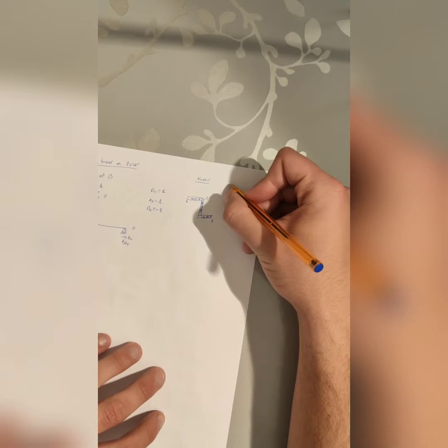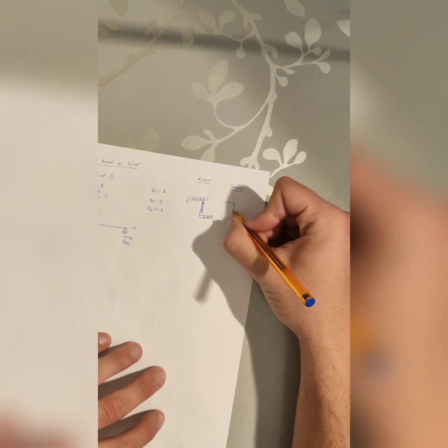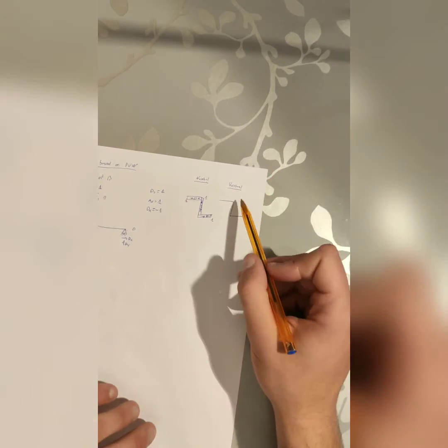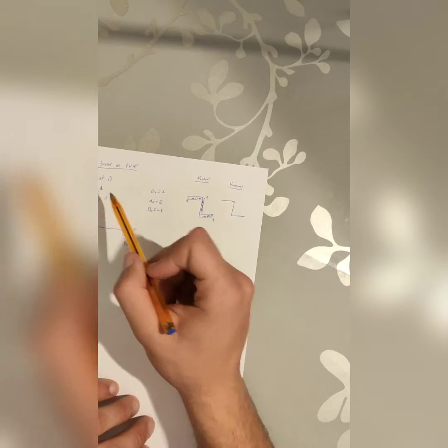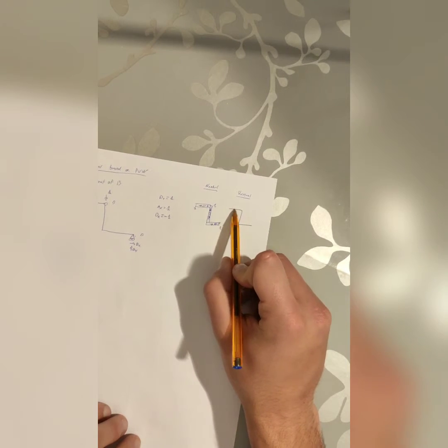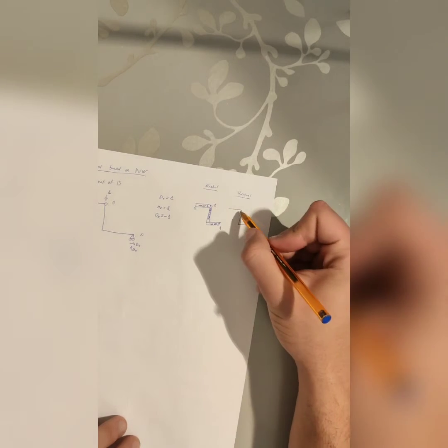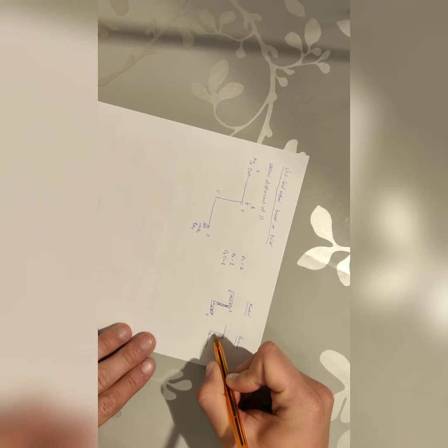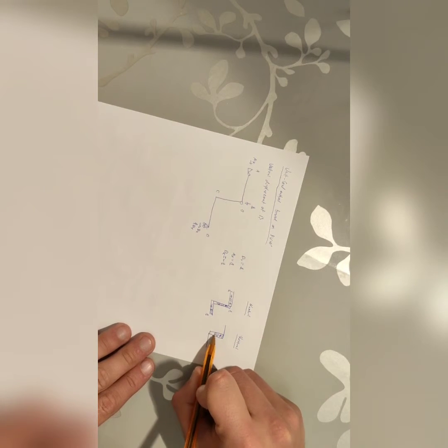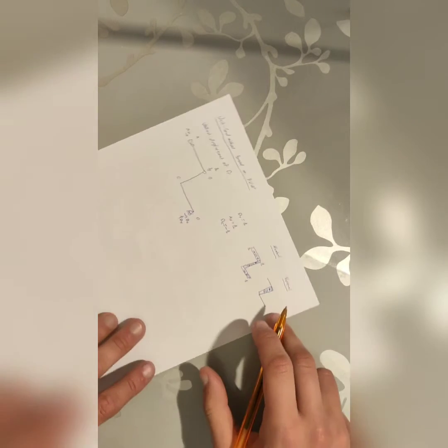Shear. Same structure. And this is very similar to the previous case for S0, when we had P here. So in this part, from A to B, there's no shear force. And afterwards, we have a shear force that, if we look like this, is upwards. On the left we have a positive vertical force, and on the right, a negative vertical force.